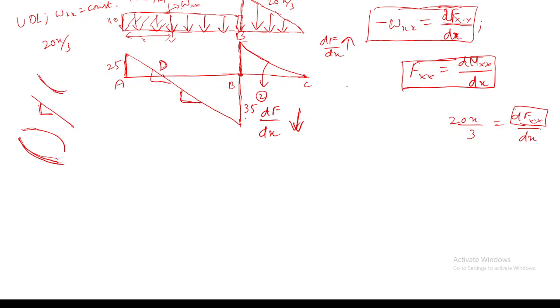From the equation of AB, we can put shear force equal to 0. Yes, that is one method, that is also correct. And then you can also find it using similar triangles. So can anyone say what is the position of point D from A? 2.5 meters. Yes, it is 2.5 meters.